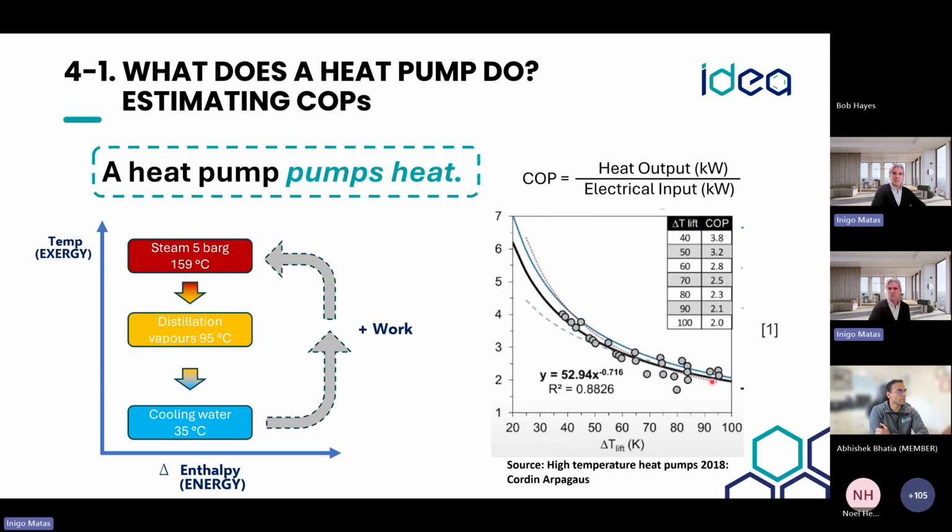I think a few years ago, people would say this heat pump can do this, or it has very good performance, or the other one. I really like this chart, prepared by the European Association of Heat Pump Manufacturers, where we can see the COP values associated with the lift that we can read on the x-axis. As the lift decreases, the COP is higher.